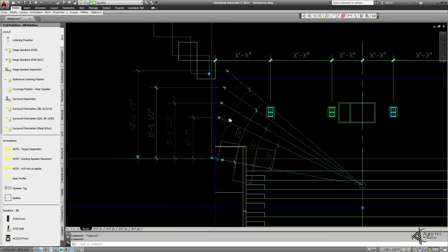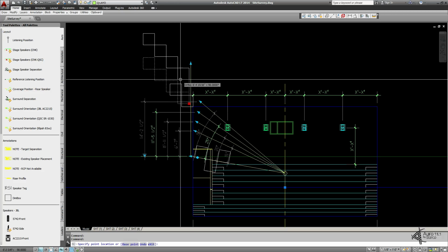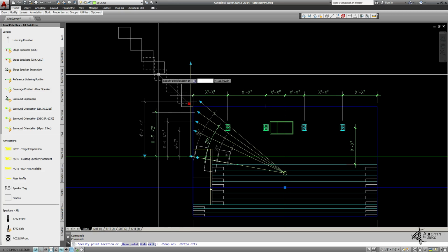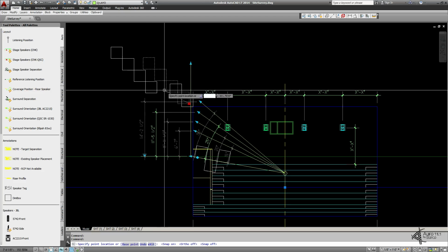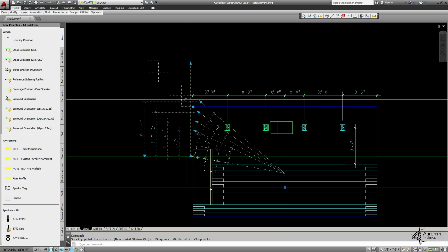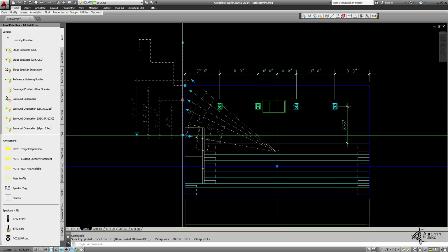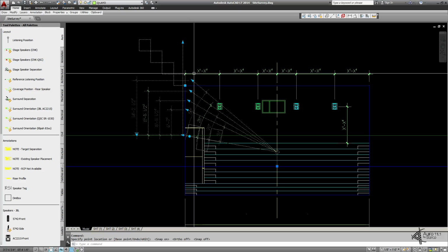So to continue describing this block, again, it's got a quick little set of offset spacers to drop on there, and those are all drawn on defpoints so they don't show up on the actual output, but it helps you line up dimensions across here.